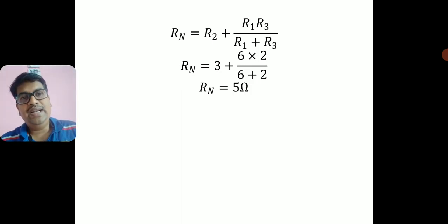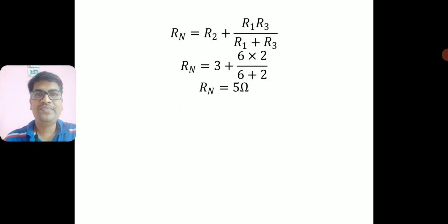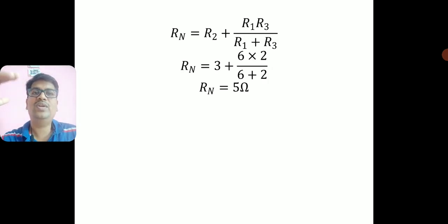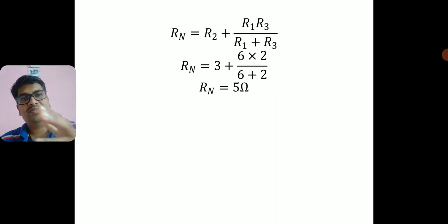So the point of observation is very important to judge which one is parallel and which one is series. If you are looking at the load terminal, R1, R3 look parallel. If you look from the perspective of current, R1 looks series and R2, R3 look parallel. So the parallel-series combination will change as your point of observation changes.